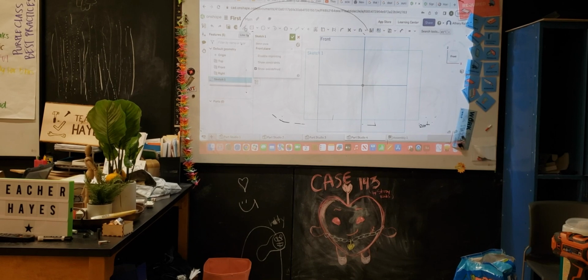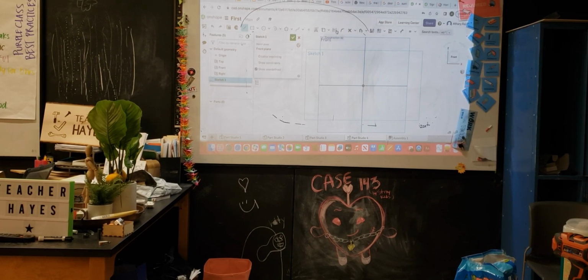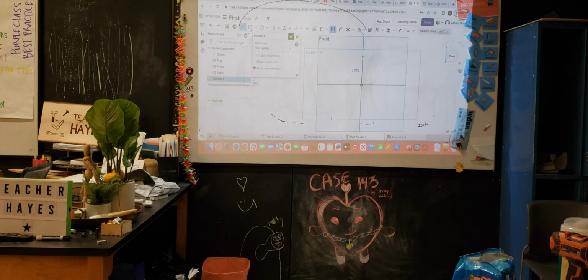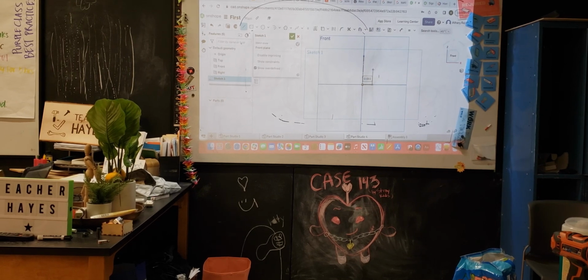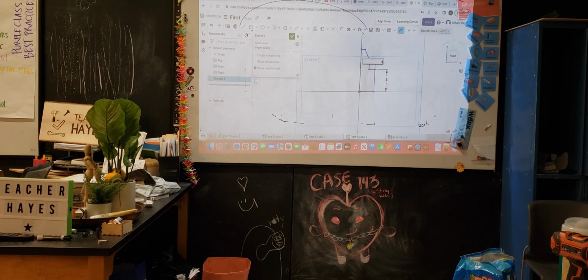So okay, I'm in my sketch. I'm gonna make a construction line at the vertical. All right, next I'm just gonna ideate out the general shape of my spacer. So I want to go in here, and then I want to draft in here, go like that. So there, I just quickly made a spacer. Now I can quickly dimension this, I put 0.3, this is 0.5. Does that look good to you?